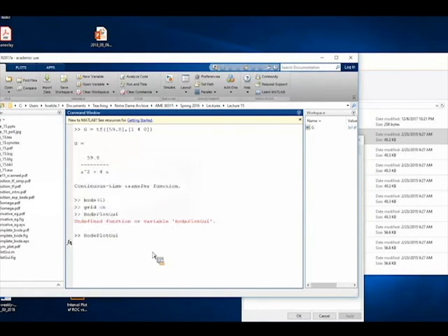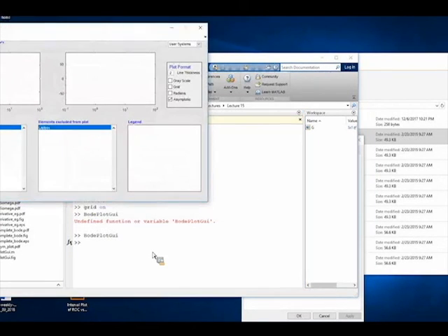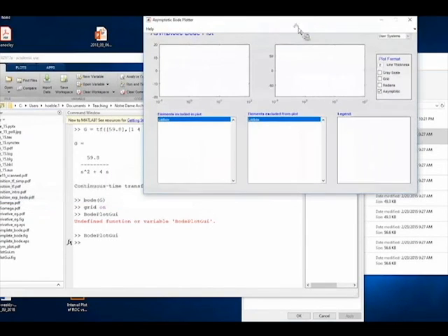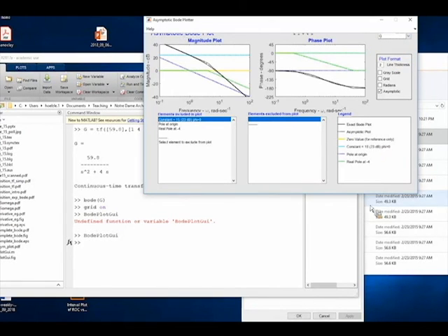All right, so if you go to Carmen, there's this GUI called Bode plot GUI. This is something that someone else wrote. I didn't, but it's available for free. And so what it does above and beyond the actual Bode plot, it gives you all the asymptotic approximations as well. So it helps if you want to check your work in terms of drawing these. It's a nice software tool to do that. We already have G in the workspace, so we can just go and say find user systems. We say G, and it's going to then plot a few things for us here.